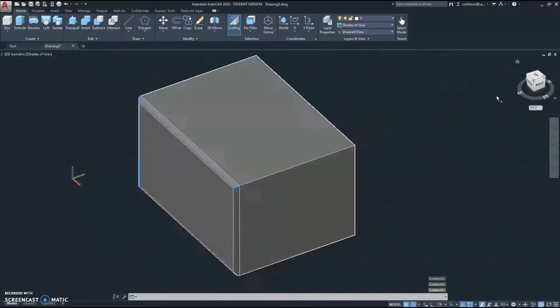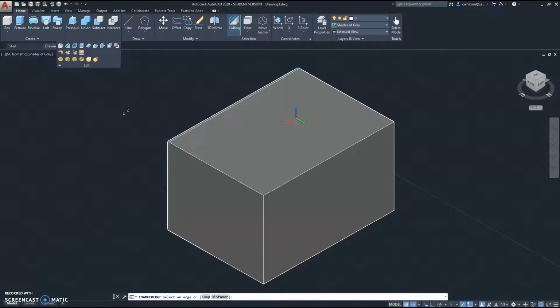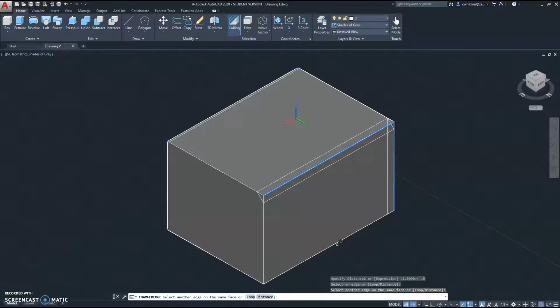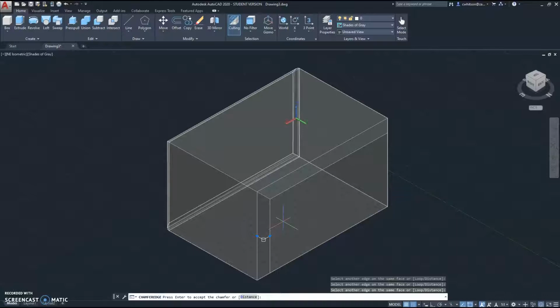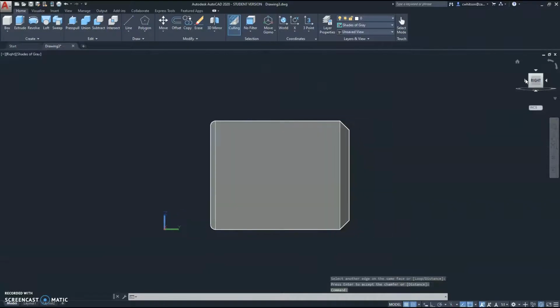And then over here on the other side, I'll chamfer these four sides. So again, it's not the one on the modify tab, it's the one on the edit toolbar. I'll select chamfer and specify the distance. Let's say 0.5, enter, 0.5, enter. You have to put in two different distances for the two legs, the vertical and horizontal leg of the chamfer. And then you select the edges you wish to chamfer, like so. Hit enter once, enter twice. And we have chamfered those edges.